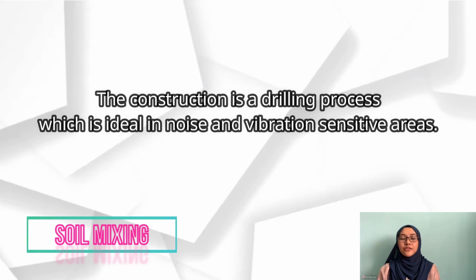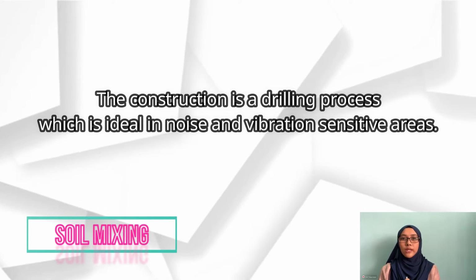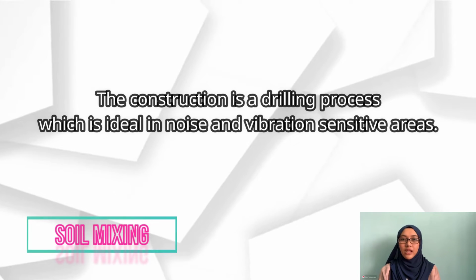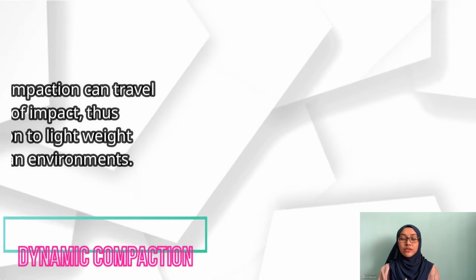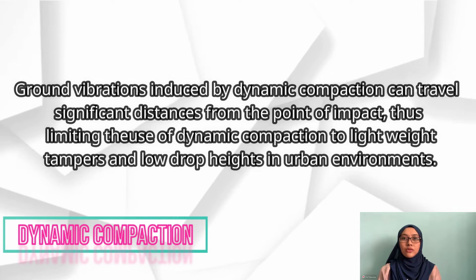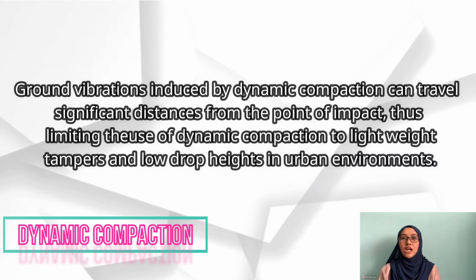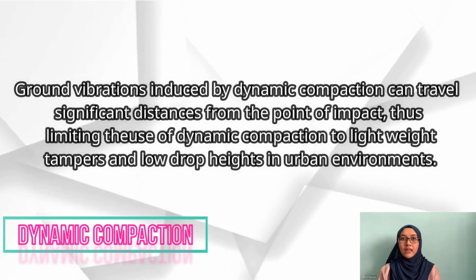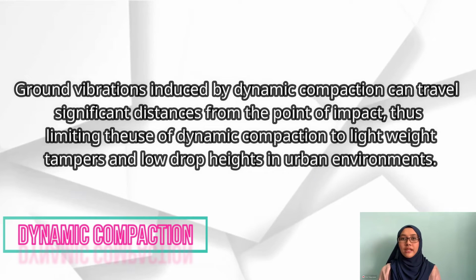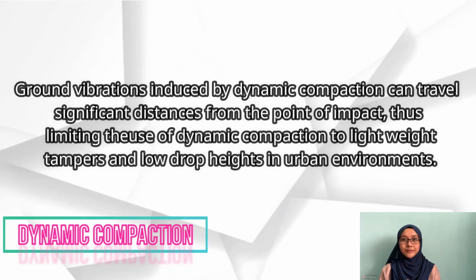Second, soil mixing is a drilling process, which is suited to noise or vibration sensitive areas. For dynamic compaction, ground vibration induced by dynamic compaction can travel a significant distance from the point of impact, thus limiting its use in urban environments to lightweight tampers and low drop heights.